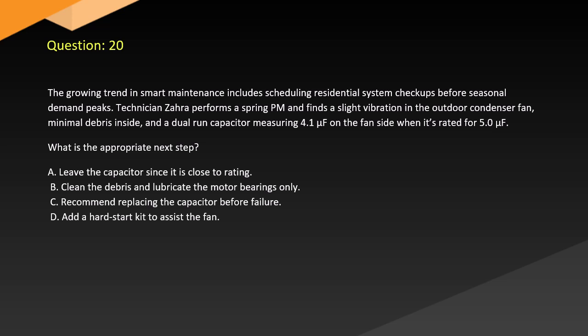Question 20. The growing trend in smart maintenance includes scheduling residential system checkups before seasonal demand peaks. Technician Zara performs a spring PM and finds a slight vibration in the outdoor condenser fan, minimal debris inside, and a dual-run capacitor measuring 4.1 µF on the fan side when it's rated for 5.0 µF. What is the appropriate next step?